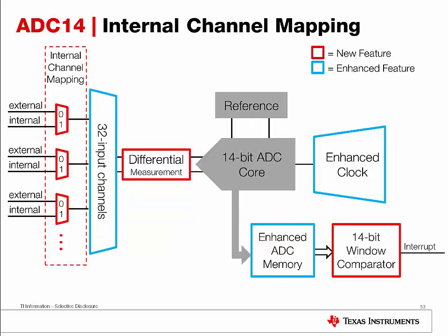Next, we also have another feature that is new to ADC14, that is internal channel mapping. Traditionally on ADC12 modules, there are some dedicated external as well as some dedicated internal channels. Some of the internal channels are the temperature sensor as well as a VCC monitor channel.